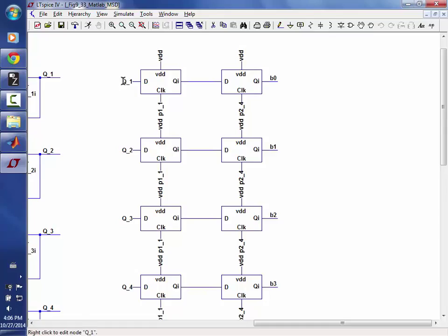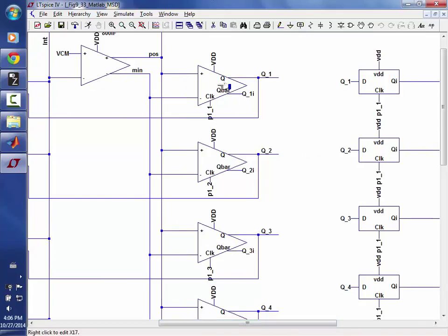Okay, so you have to play around with this, but if you don't know digital design and you don't understand how to clock a flip-flop, this is going to be a problem because you are clocking your comparator here and the D latch at the same time. Well, it's going to grab the previous value. Okay, so you have to make sure you understand what's happening there, because if you clock it slightly after and this guy's not making full logic, you'll make mistakes. Does everybody follow that? So if I clock them at the same time, this value is sitting there all set up, it captures, and then this one makes another decision and has a whole clock period to make the decision before I clock it in again.